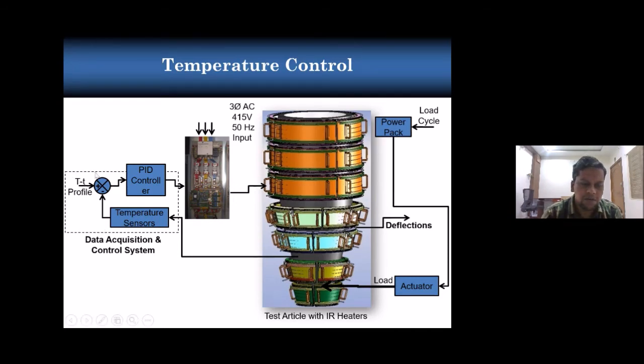Now I have a time temperature profile fed into the system with dedicated software for our facility, which will communicate to every system of the facility. Now we have a PID controller. Through the PID controller it will interact with the thyristors, and the thyristors are directly connected to the heater.